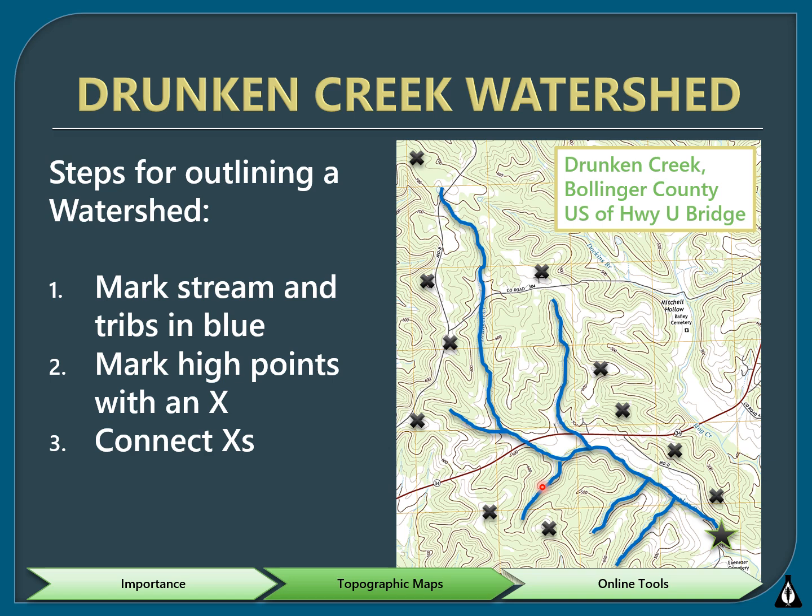And then you're going to want to put an X or mark somehow all of the ridge tops that you see surrounding the water features. And then you'll just go through and you'll connect the X's following the topographic lines. And that is how you can outline a watershed.